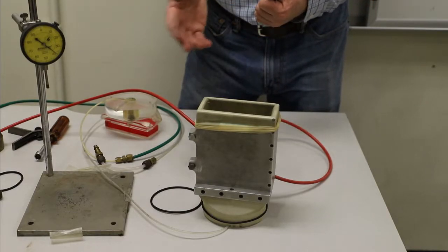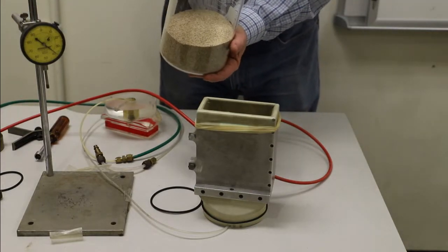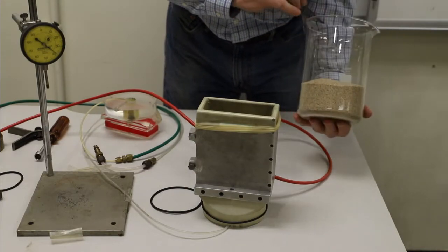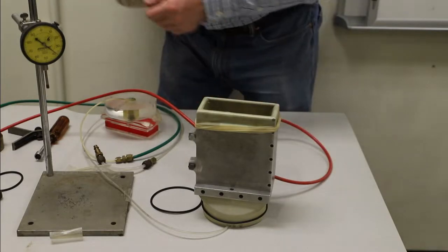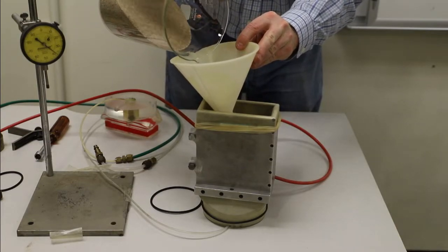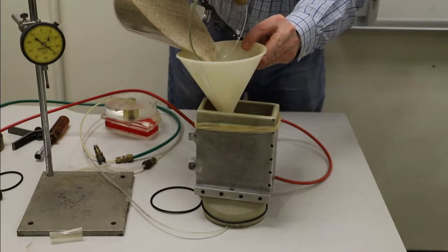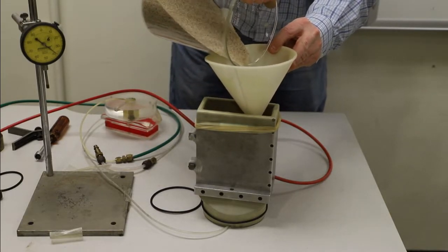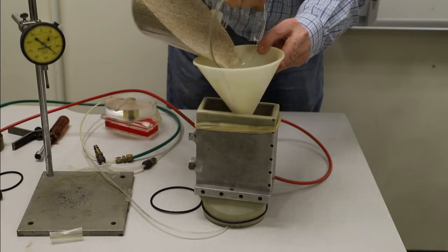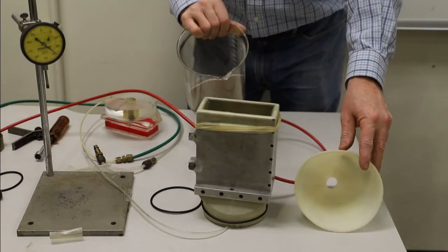So we're going to actually build the specimen in a few layers, and along the way we're going to apply a lot of energy. You'd want to have the mass of the beaker with the sand, and probably good to have a funnel so you don't spill, because we're going to measure the sand that's left over at the end and subtract in order to tell us how much sand is in the specimen. So that's about 1/3 full.